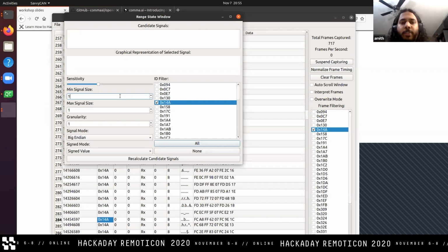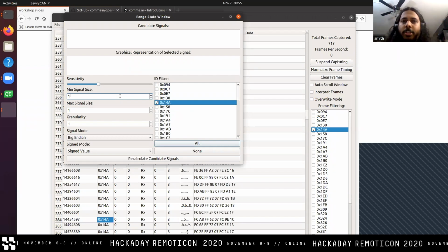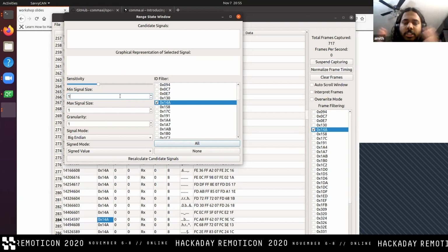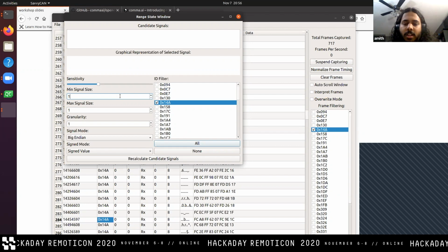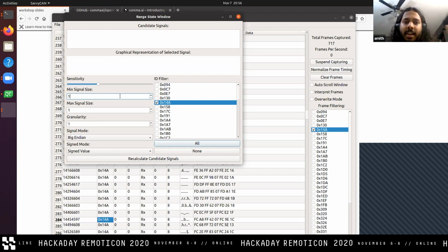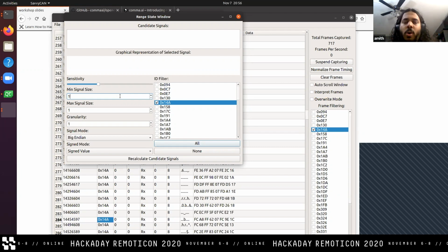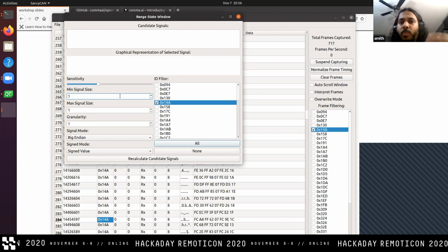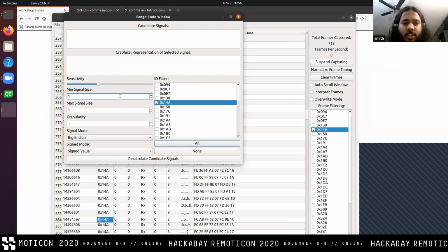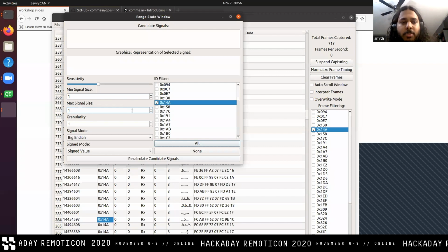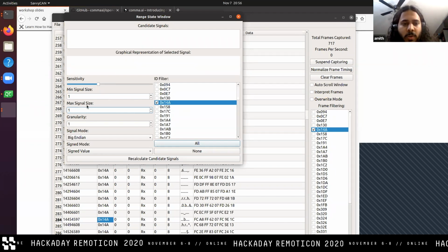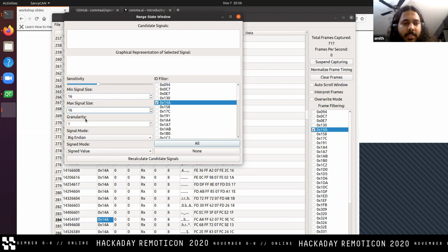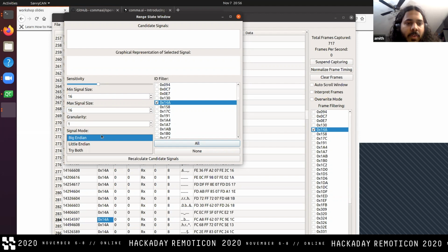One way of doing it is to basically try all permutations of how you can slice up that 8 bytes into smaller pieces, into signed integers, and do all these other permutations and just graph them and see what data makes sense. So that's kind of what it's doing, but in a more sensible way. So we know our signal size is 2 bytes. So this is 16 bits, 16 bits. And we can try both.